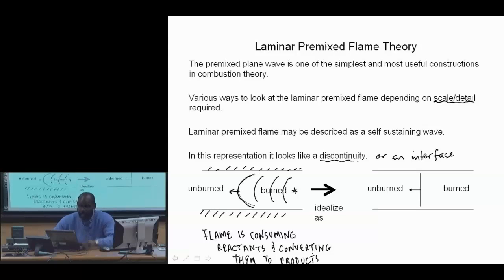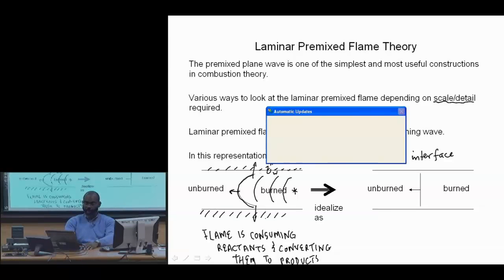Now, I show some curvature here. So there are all sorts of factors that impact whether a flame is going to be curved or not. For a long time, people thought that the basic issue in terms of curvature was the boundary condition on the wall of this channel. So the assumption was that it's heat losses through the wall that might inhibit the propagation process at the wall relative to the propagation, for example, along the center line. So, commonly you have a cold wall of some sort.